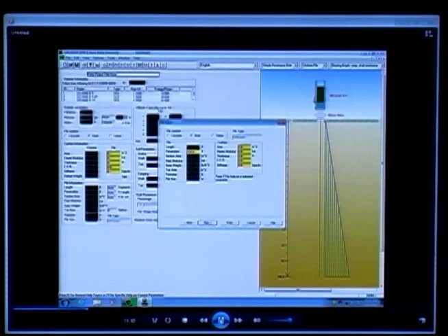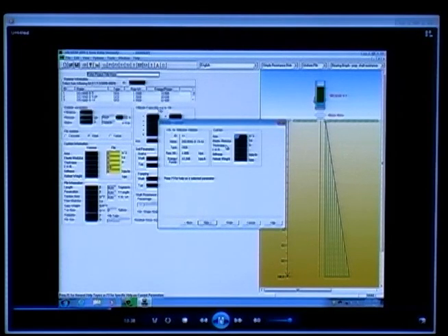The contract pile length of 75 feet is input for the length. Cross-sectional area of 16.8 inches squared, default steel modulus of 30,000 ksi, and specific weight of 492 pounds per cubic feet are accepted. For a pile toe in clay, a box area of 100 inches squared and a box perimeter of 3.33 feet are chosen. The pile size is 10 inches. Press Next after completing the pile input.